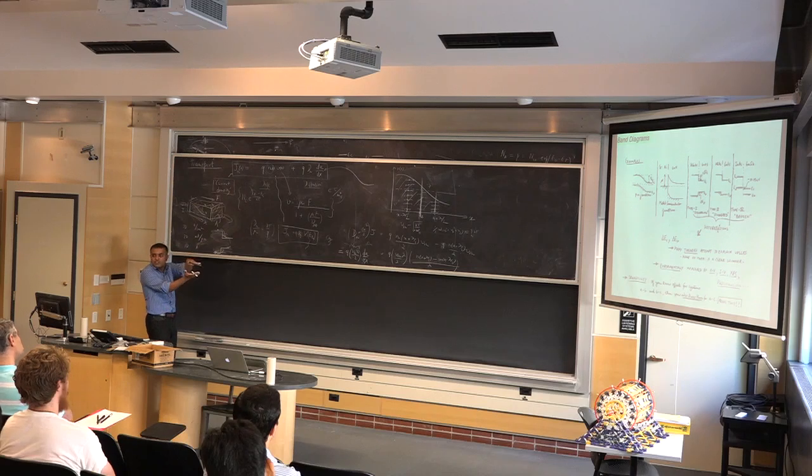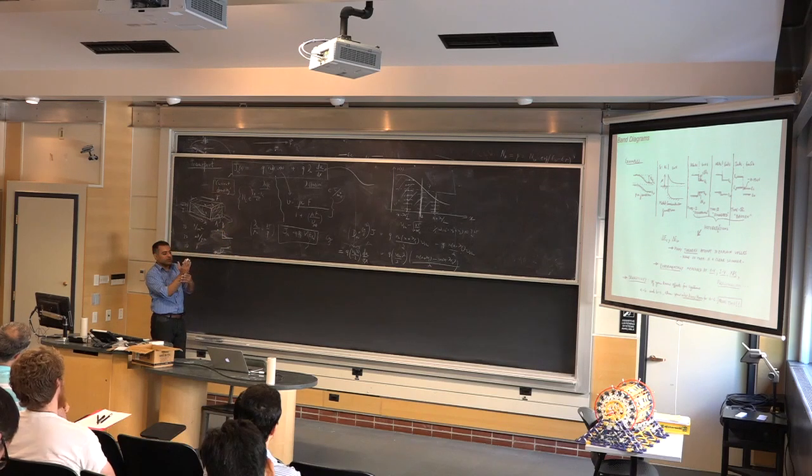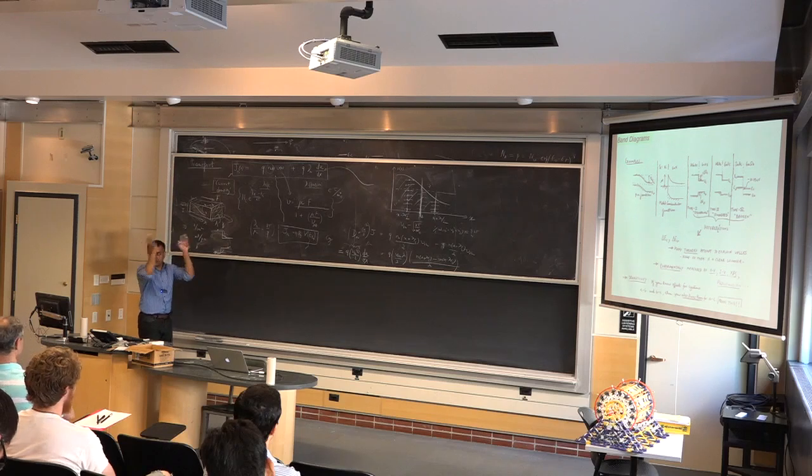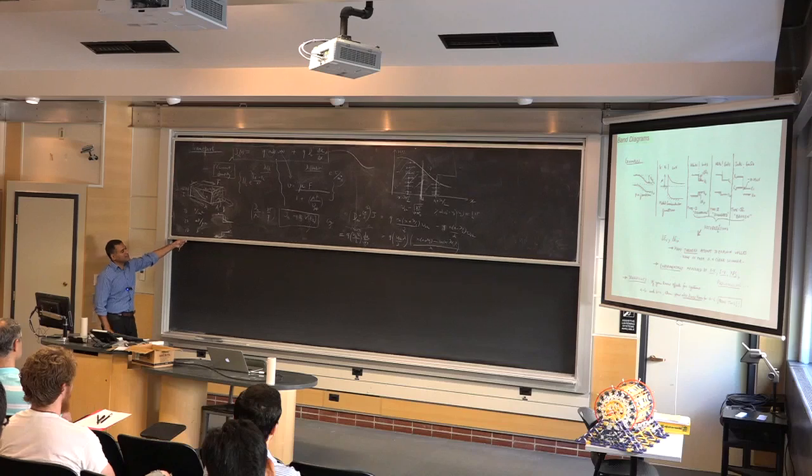In a graded junction, it's easy to see, but in an abrupt junction, that happens much faster in some sense, right? And the field is in a very small window where the junction is. That's what the field is. This is like a delta function field. In that window, you have a huge field. It just kicks the electrons and holes into the same direction. So that's a heterojunction capability.